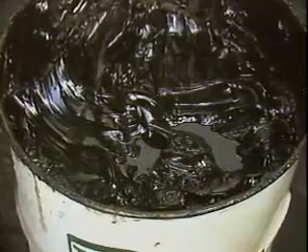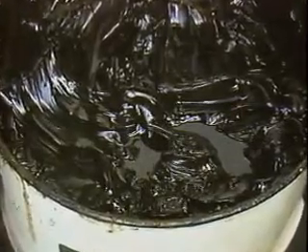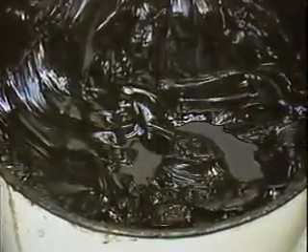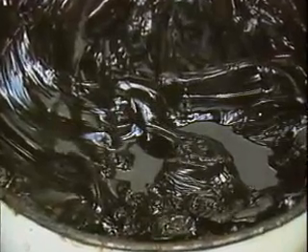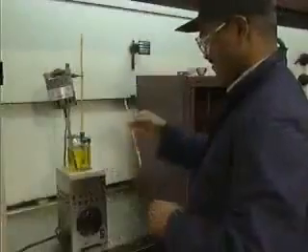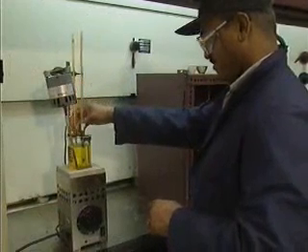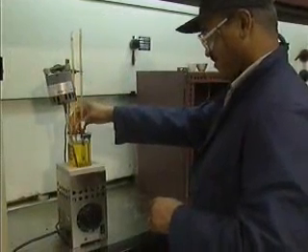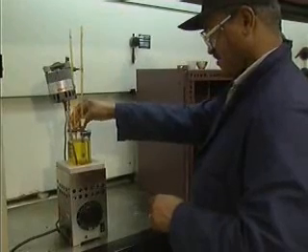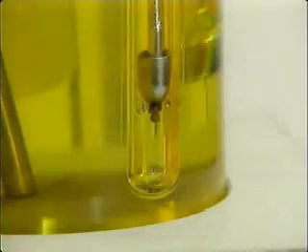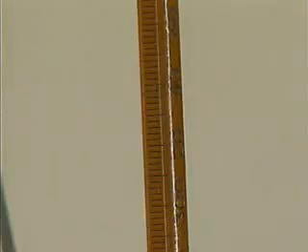Certain properties unique to grease determine the appropriate grease for a particular application. One such property is drop point. Drop point refers specifically to the melting point of a grease. The term is derived from the method that's used to measure this property. The grease is heated slowly until fluid begins to drop from the grease. The temperature at which the drops form is the drop point.